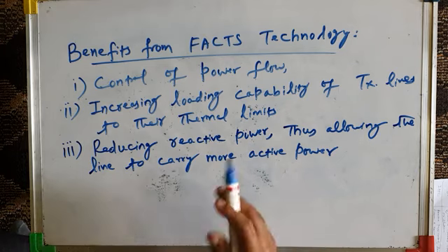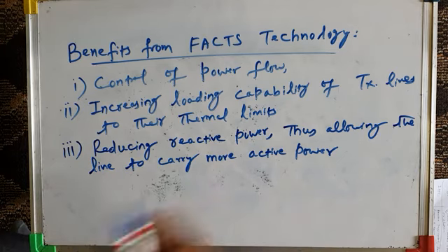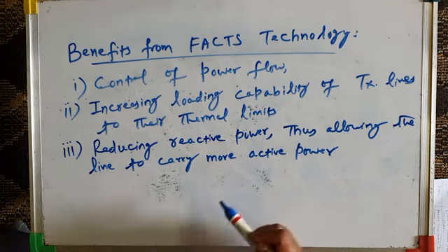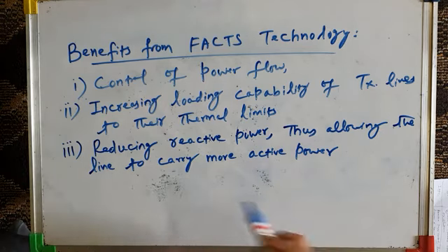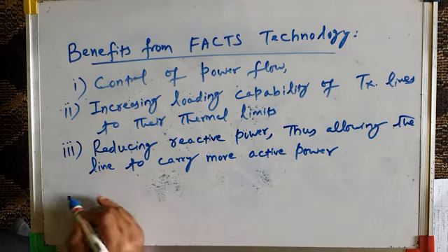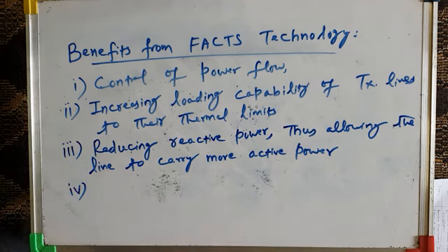And hence, when reactive power flow on the line is reduced, the same line can carry more active power, can carry more megawatts and supply more power to the load. So by using FACTS devices, reactive power flow over the lines can be reduced, thus allowing the line to carry more active power. So this is another benefit from FACTS technology.